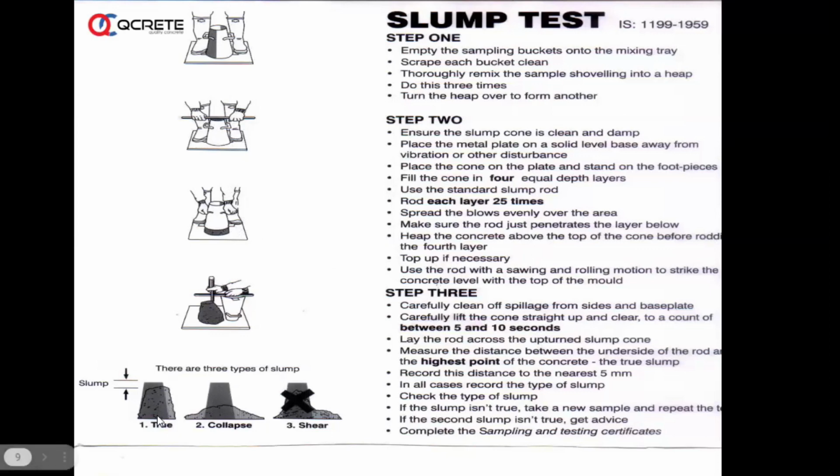This is the best slump, that is true. It shows a cohesive good mix. This represents a collapsed concrete, which is free flow concrete. And then shear, it should not have a shear at a slant, it should not fall like this. So these are some tests which will indicate the quality of concrete when you are receiving it at site. Actually, this has to be observed.